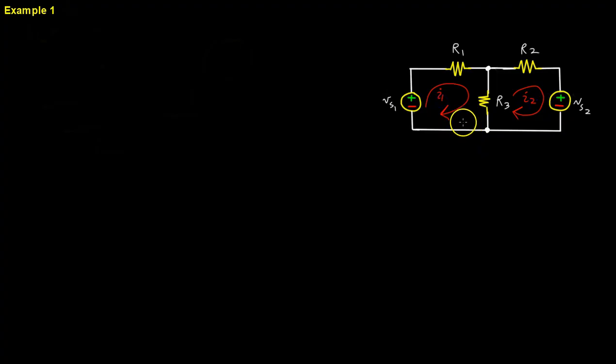As we said, as part of one of the instructions, we have to define some currents for the meshes. These are called mesh currents. So we define mesh currents. Then what we always do for circuit analysis problems is to define a voltage drop according to passive sign convention, based on previous lectures. So I'm going to define some voltage drops. I'm going to put the pluses here and put the minuses here, meaning the current should flow from positive to negative, and so on and so forth.